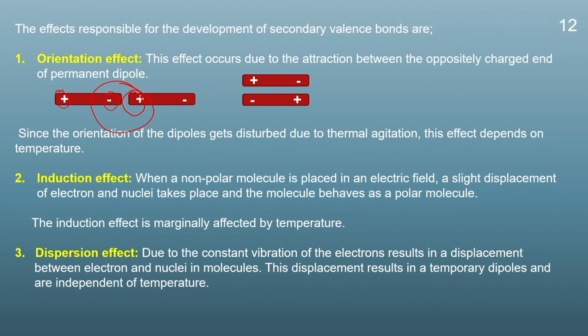Similarly, in this orientation, the positive end and the negative end will be attracted. Because of the orientation of these particles, there will be an attraction between these dipoles. We need to remember one thing: the orientation of the dipoles gets disturbed due to thermal agitation. That means if we increase the temperature, then the orientation of the dipoles will get disturbed, and so the effect will also get disturbed.